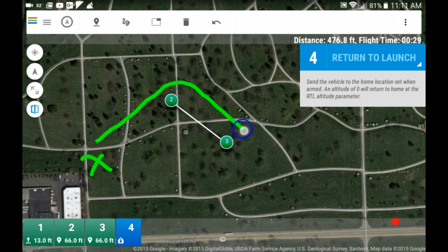It's going to head to waypoint 3. At waypoint 3, it's going to receive a return to launch, because that's what we programmed. And it's actually going to come back home and land, just like a normal return to home that you would issue via the controller. So that would be considered a fully autonomous mission in Tower.